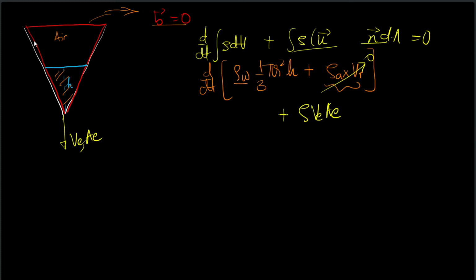So if you consider this to be the control volume, there is some liquid which is exiting the domain, but some amount of air will be entrained from this. There will be some entrained air which will enter this control volume. So there will be some rho air times V entrainment times area of base. But again, rho air is going to be quite negligible compared to rho water, and V entrainment will also be quite small.